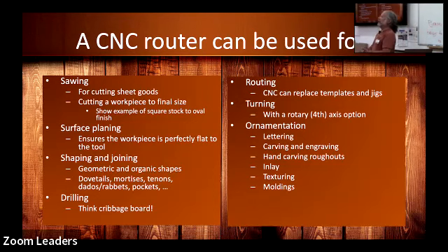If you need to surface plane, I wouldn't surface plane a 4x8 sheet of plywood on that thing. It'll take quite a while, but there's some very precise routing and joinery operations that you might want to do on your machine, and you can surface plane a piece of material on it and make sure that it's absolutely parallel to the bed. Very handy for doing that kind of work. And one of the first things that you'll do with a surface planer is to make sure that your spoil board is flat and level as well.